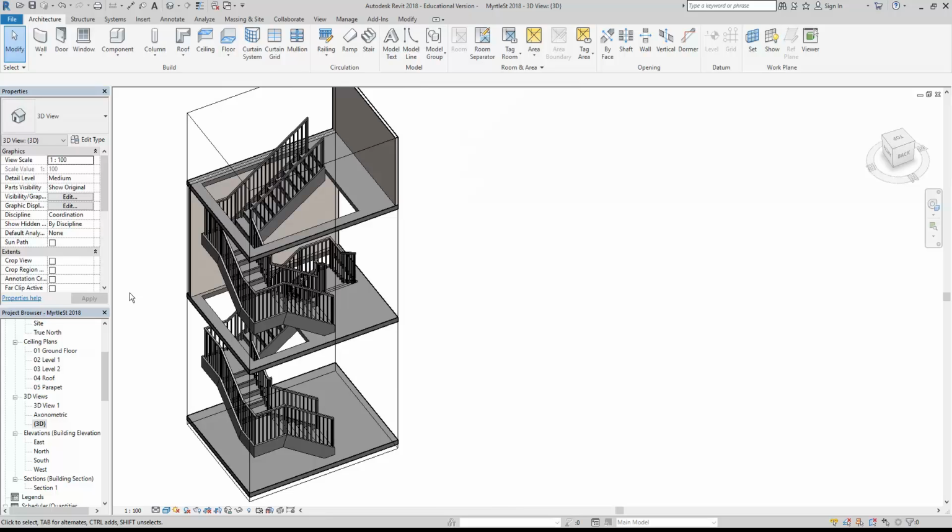So, is there like a minimum? Oh, look, yeah, there are some guidelines for that. Otherwise, you've got to do some pretty detailed calculations. But how does it work again? It's 2/3 the height in your width. So whatever your height is for the shaft that you've done, you can ventilate at least 2/3 of that.